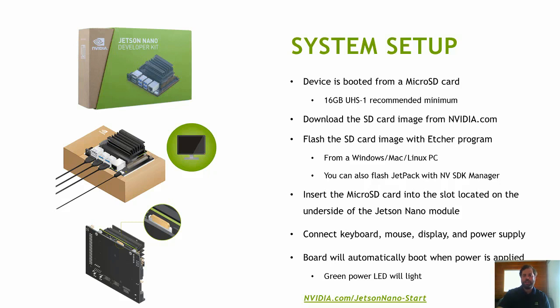There's also a second way to flash your Nano, and it's similar to how the previous Jetsons were flashed with Jetpack. First, you insert your blank microSD card into the dev kit, connect its micro USB and Ethernet port to the Linux host PC running Ubuntu, then enter it into recovery mode using the J40 button header. Then you use the NVIDIA SDK Manager application running on your host PC to flash the OS and install the Jetpack components. The NVIDIA SDK Manager allows you to select exactly which Jetpack components you wish to have installed, and it's how the production Nano modules that use eMMC will be flashed because they don't have SD cards.